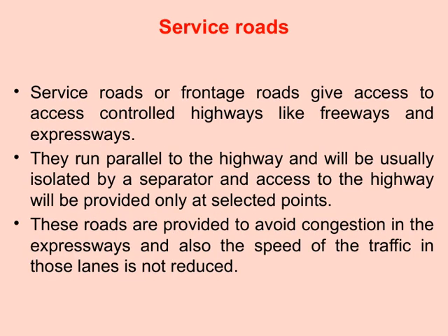Service roads, also known as frontage roads, play a crucial role in our highway system. They provide access to access-controlled highways like freeways and expressways, which are designed for high-speed, long-distance travel. These roads run parallel to the main highway, creating a separate pathway alongside it. Usually, you'll notice that they are isolated from the highway itself by a separator, ensuring safety and clear separation. Access to the highway from these service roads is only allowed at specific points, which helps manage traffic flow efficiently.